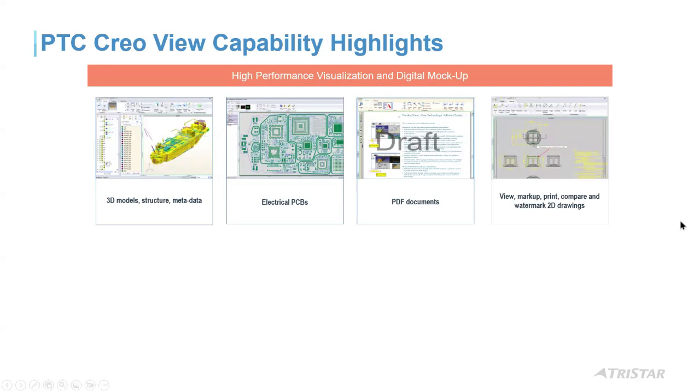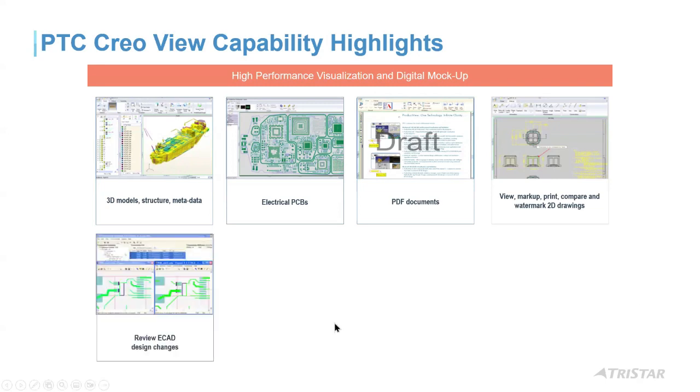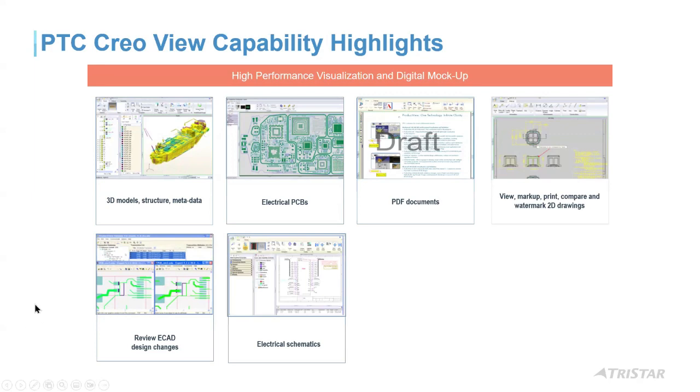On the drawing side, if you're creating 2D drawings, whether that's a vector file like an HPGL from Creo, or you're publishing them to PDFs, you can also mark up and view these drawings with this viewer. There are also comparison options with this viewer. So you can compare what's different between different revisions or different iterations of a part or a 2D drawing or an ECAD design. So there are add-ons that are industry specific to what you need to do.